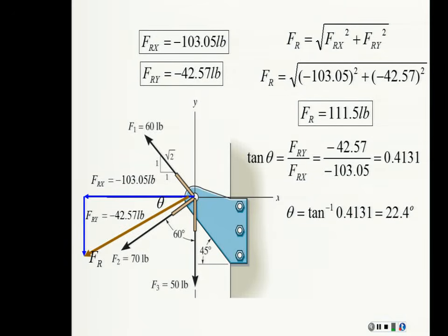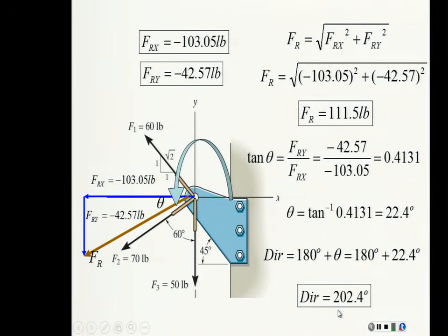Okay, that is wrong. That problem is wrong. Because if you read the original problem, or even if it doesn't say, the problem is not asking me for this angle. It's a counterclockwise measure from the positive x-axis. And even if it doesn't say it, when you calculate an angle, the result should always, unless otherwise stated, be measured counterclockwise from the positive x direction, which is this one. So this value is correct, but the result is going to be plus 180, and that's the correct direction.